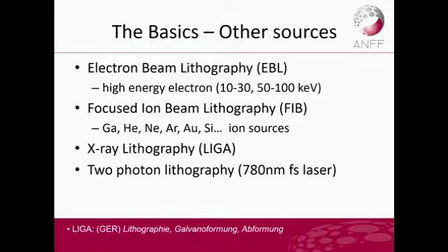Alternatively, focused ion beam lithography has been used. This is by basically sputtering atoms with another ion in high vacuum. So the state-of-the-art systems are the helium system, but the mainstream systems are gallium. The biggest advantage of the helium system is you don't have any contamination, whereas if you use gallium, you actually dope gallium all over your feature surfaces. So both of these two charged beam lithography tools don't require a mask. Instead, you use the computer to generate your design and raster the beam according to your design.